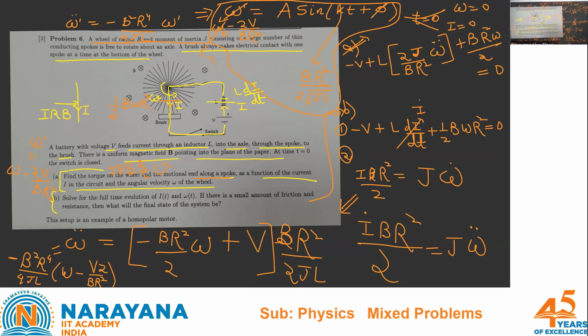At t is equal to 0, angular velocity and current both are equal to 0. So omega dot is also 0 at t is equal to 0, because omega dot depends upon current and omega itself is 0. So put t is equal to 0 in d omega by dt, so two variables are there, that phi and that A will be eliminated, and that will give you omega as function of time. Once omega comes, you will get your current as function of time and everything will fall in place.